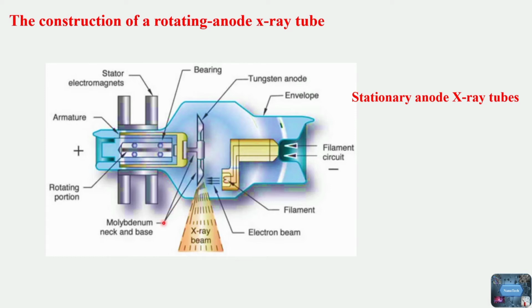The entire X-ray tube is contained in the protective housing. The housing is usually made of metal such as stainless steel, and it serves as a very strong support for the rather delicate X-ray tube. The X-ray tube is placed in the housing and then the housing is filled with oil. The oil serves two major purposes. 1. It helps cool the X-ray tube, just like oil in your car helps cool the engine. Additionally, the oil helps insulate electrically for safety. And one additional thing it does: if you notice where the primary beam exits the housing, the X-rays must pass through a small thickness of oil before they emerge from the tube, and this contributes to minimal filtration or absorption of the X-ray beam when you make an exposure.